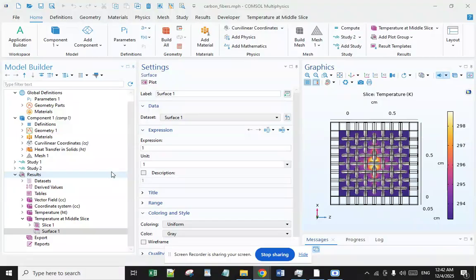which may be either randomly orientated in usual mixing, casting, coating via Dr. blade or spraying techniques, or orientated via electrophoresis or electrospinning. For example, for unidirectional reinforcements, the rule of mixtures may be used to predict the thermal conductivity in the direction parallel to the fibers.